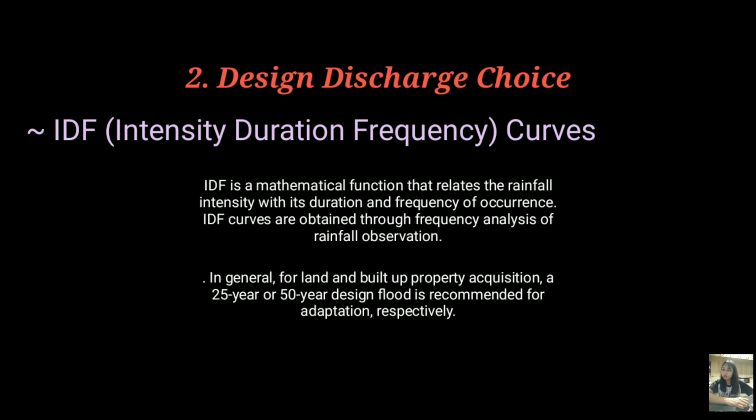IDF curves are also necessary for efficient operation of the energy dissipation system by considering a design discharge which may be lower than the IDF for dam safety. The use of this flood discharge with standard specification or other factors affects the performance and the energy dissipation arrangement in the most efficient manner.